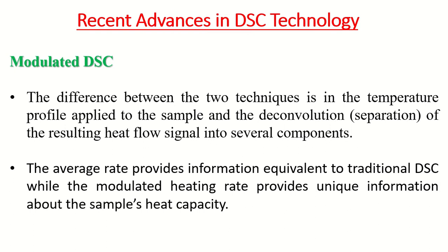Instead of the simple linear temperature change used by differential scanning calorimetry, modulated differential scanning calorimetry uses two simultaneous heating rates, an average or underlying rate similar to differential scanning calorimetry plus a sinusoidal or modulated heating rate.